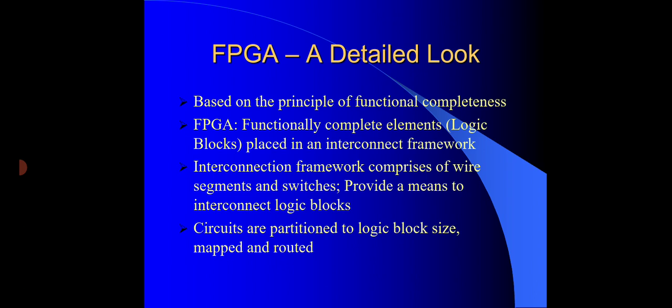Field programmable gate arrays are prefabricated silicon devices which are electrically programmed in the field to become almost any kind of digital circuit or system. For low to medium volume production, the FPGA is a very cheap solution, and it has a much faster time to market as compared with other integrated circuits.